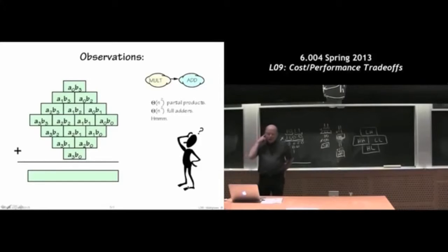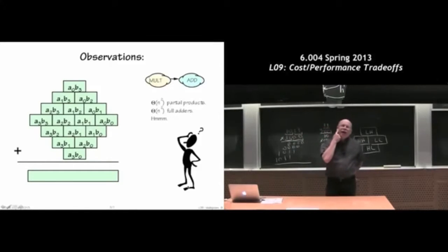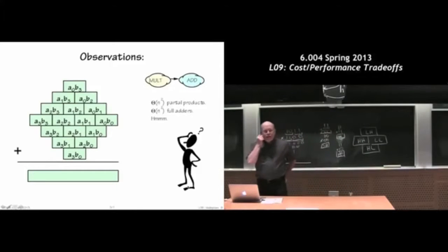So the first observation is that treating this as two separate problems, a problem where I have to build partial product circuitry and a problem where I have to build adder circuitry, we might be able to get a better insight about what building block, and so that seems to require at least a couple building blocks. What I'm going to do is suggest that, look, it looks like we have a full adder for about every partial product. Maybe we should combine the two.